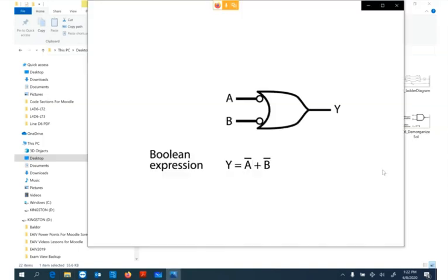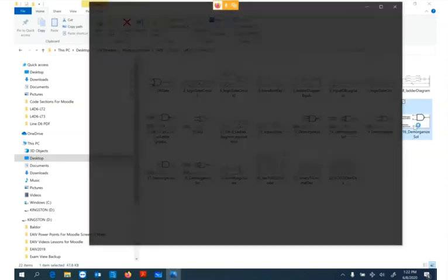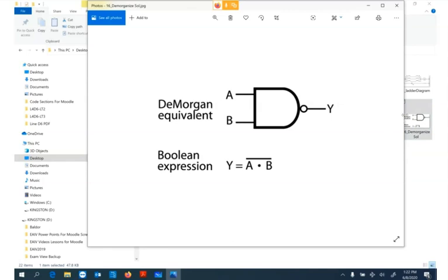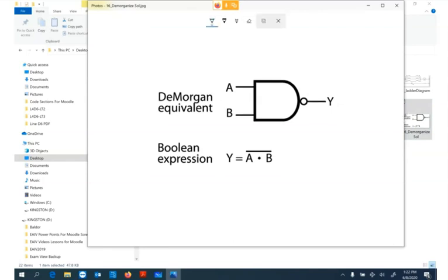So De Morganize this instruction. So we've got not A or not B equals Y. We change it to an AND instruction, and we've negated. Two negatives make a positive, so the two ones over there would make the opposite, a 0 here and a 0 here.